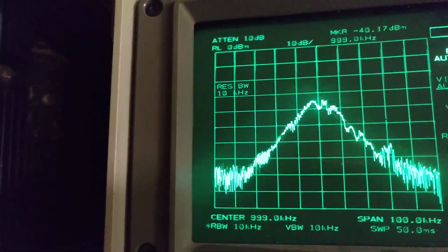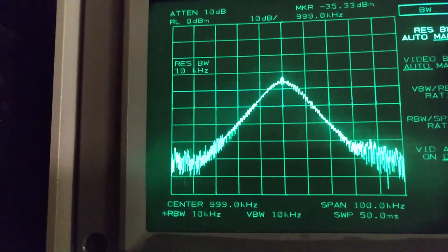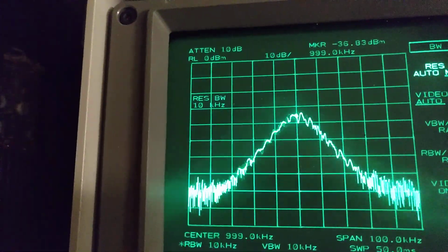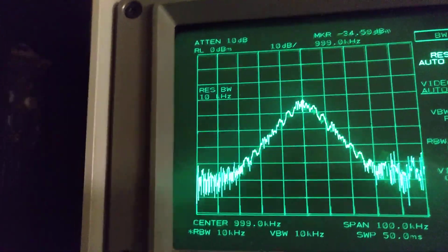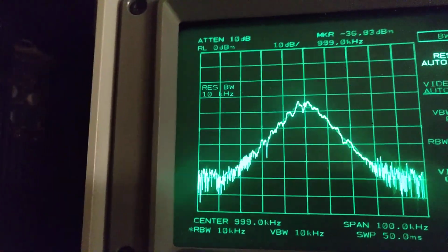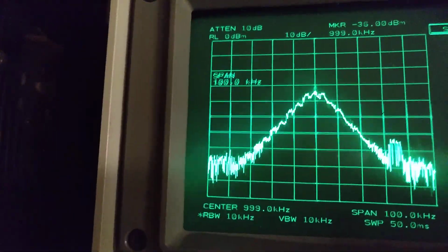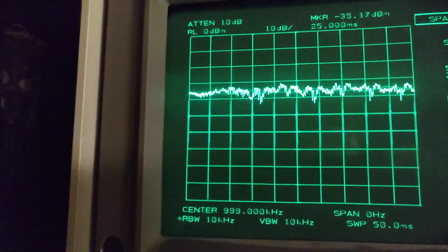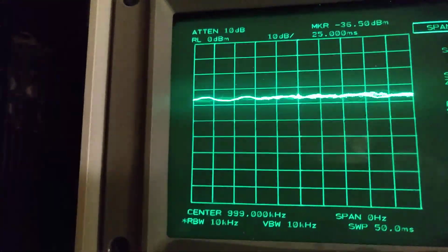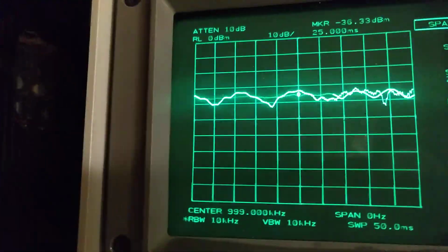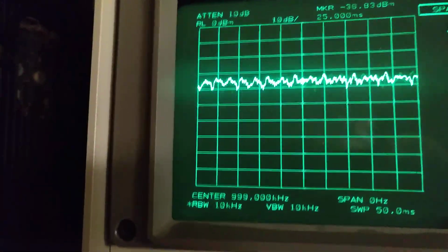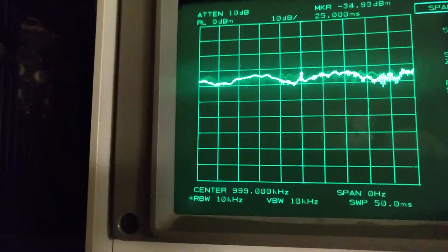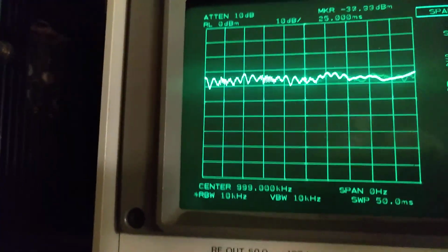So now I'm taking all the amplitude modulation, and you see that the measurement is not stable because it is amplitude modulated. If I go to zero span, I see clearly the modulation. Now I am in logarithmic scale. If I go in linear scale, I can see much more modulation, sometimes till zero, but you understand that it is signal modulated. I return to the last span.